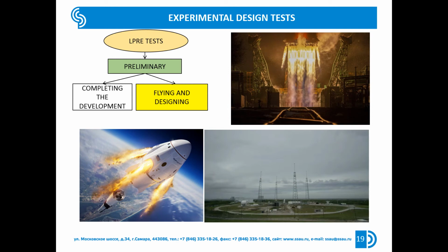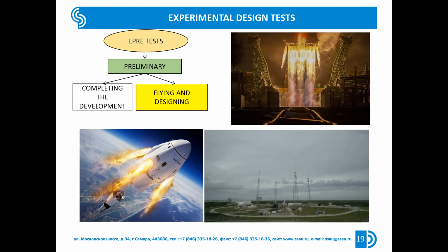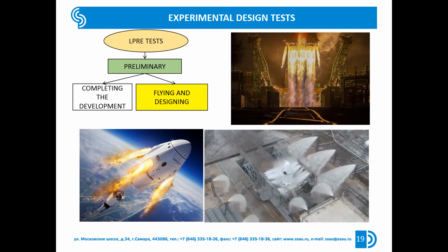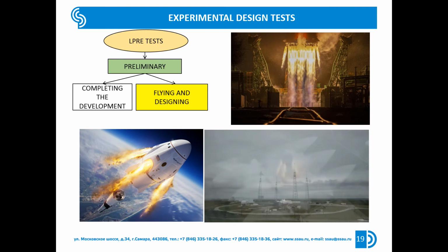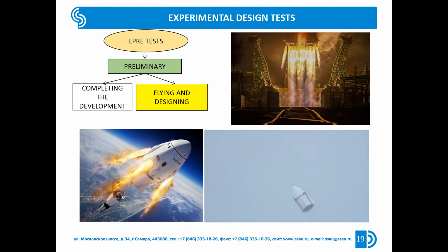A final conclusion about the performance of the LPRE under actual operating conditions can only be made based on the result of flight tests as part of the rocket system for which it was designed. The flight development tests shall be carried out according to a program agreed with all the organizations concerned. When developing the methodology for processing and analyzing test results, special attention shall be paid to the adequacy of the selected scope of parameters to be measured and the accuracy of their measurement.